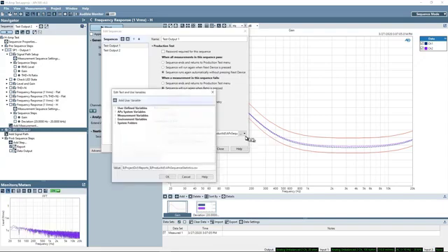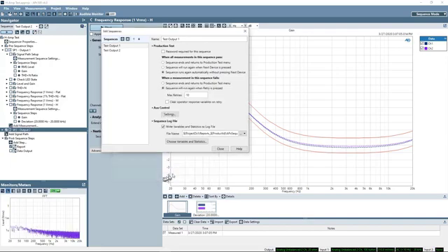Let's just go in and look at some of these variables. The folder is the project dir, which is the folder containing the APX project file, followed by reports underscore the product ID. That's the name of the folder, and then the file name is apx sequence statistics.csv. If we look at test output 2, you can see that here we were set to have the sequence run again when the next device is pressed, not to automatically go to the next device.